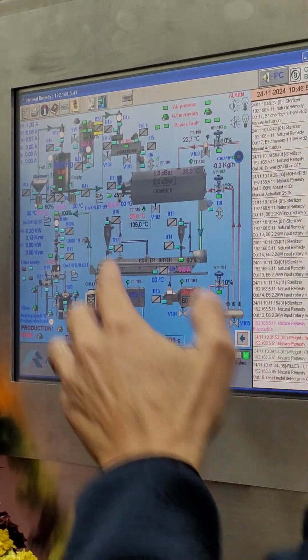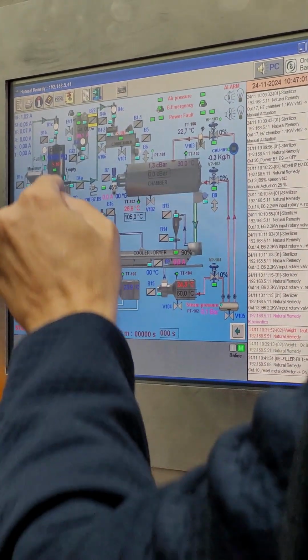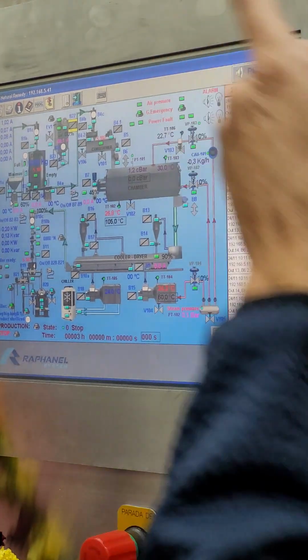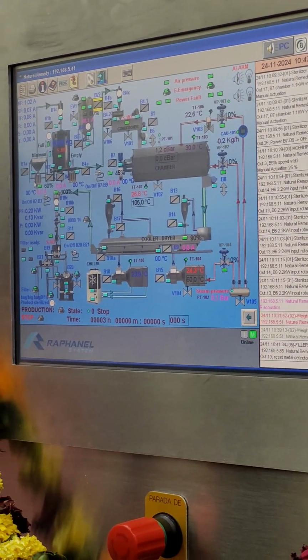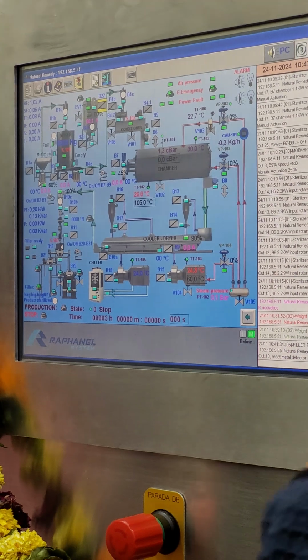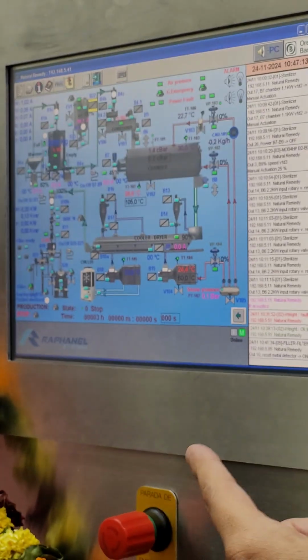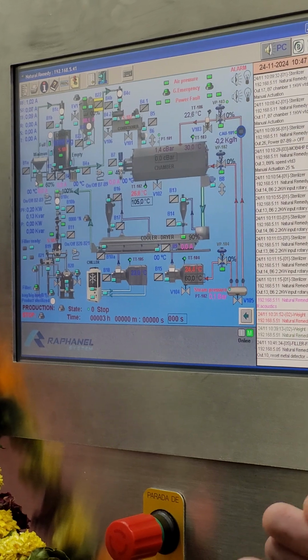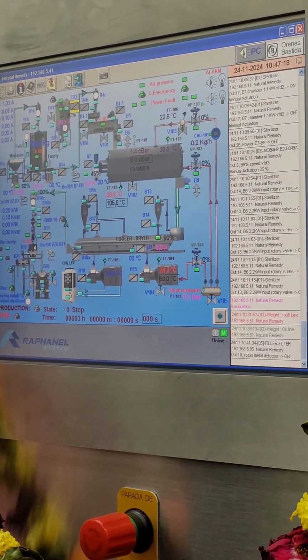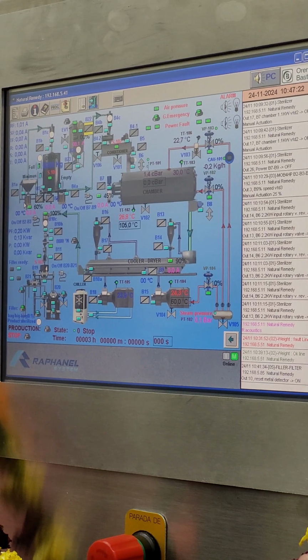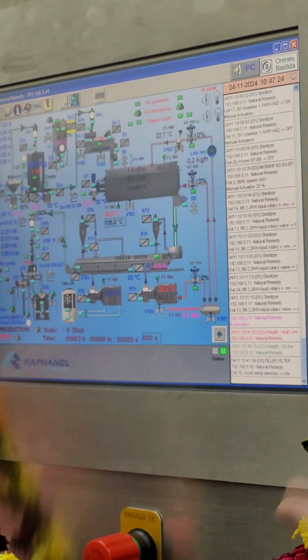This is the reason why, for us, the most important thing in calibrating the doser is not how many kgs are inside. For us, it's the same, 1 ton and 10, 1 ton and 20. It's not relevant, it's only for information. But the most important is to calibrate 0, when it's empty. We have to know what is empty because we have to cut steam.